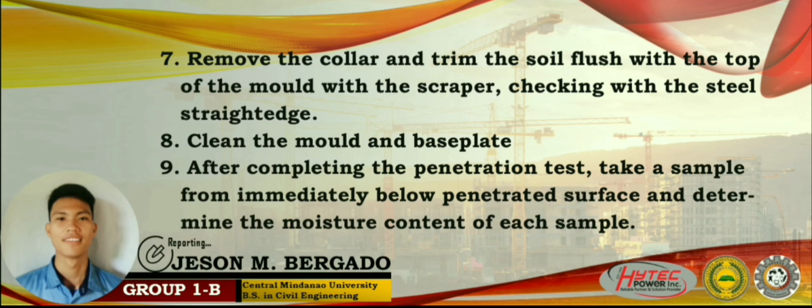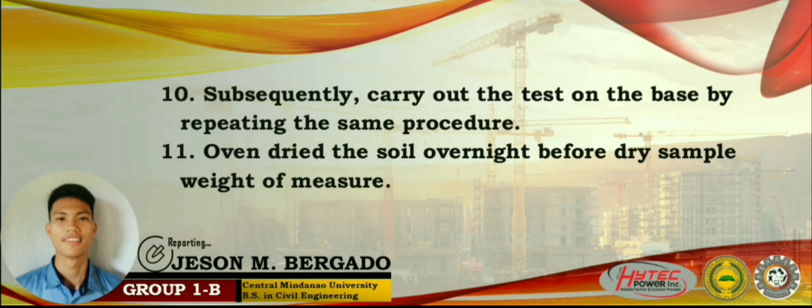And after completing the penetration test, take a sample immediately below the penetrated surface and determine the moisture content of each sample. Then subsequently carry out the test on the base by repeating the same procedure. And then lastly, oven-dry the soil overnight before measuring the dry sample weight.